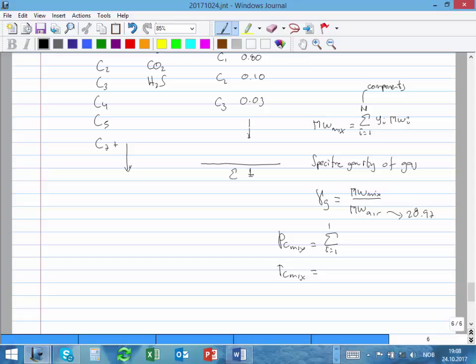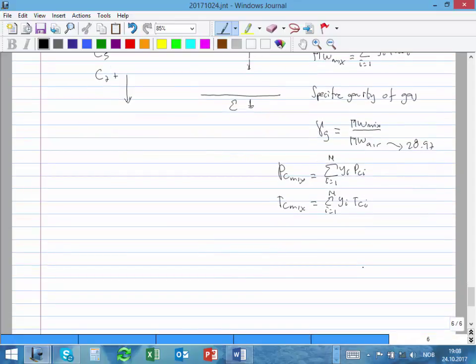Reservoir, okay. Yes, so yi, PCi, and okay, we are not exactly on reservoir. We need some of the tools from reservoir. Okay, but to make your life simple, instead of giving you the mixture, I'm going to give you a correlation, a function that was published. I think it is called the Sutton correlation, and that is just a function of gamma gas, and the PC and TC of the mixture is just a function of gamma gas. Okay, just to make your life simple.